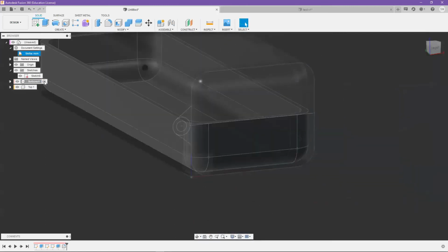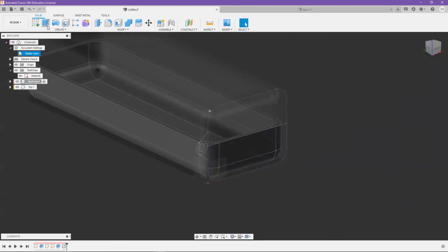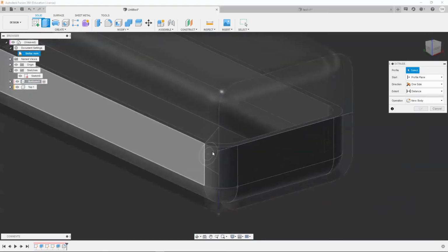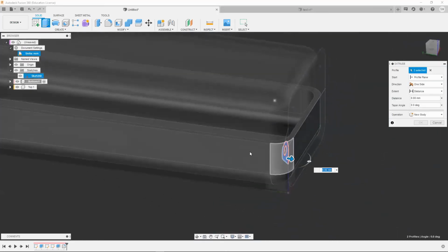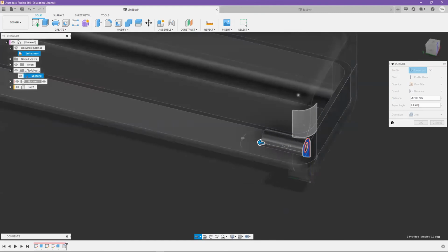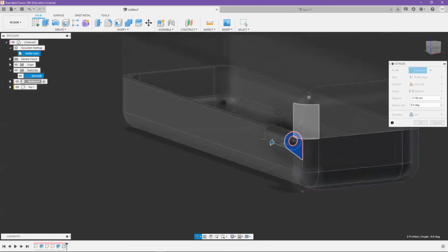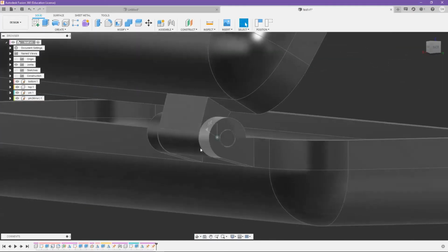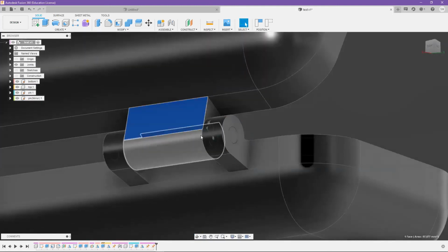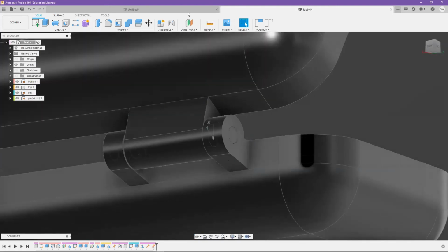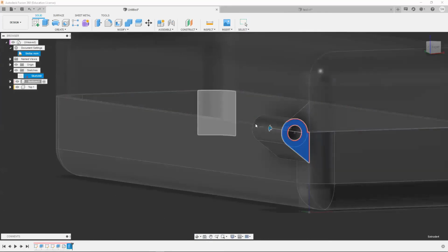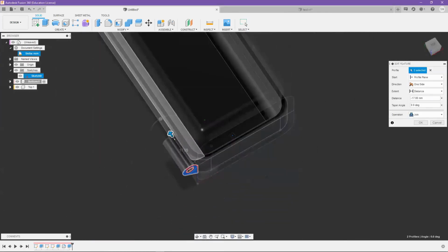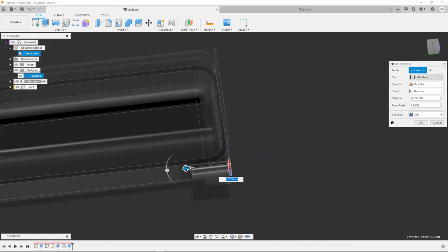So now we're already in the bottom workspace. That's fine. If you press Q or go into extrude, select this and this for the hinge mechanism on the bottom. If you drag this, you can kind of see what I'm going for. I'm going for this bottom part right here, or this top part. It could be either or, but it's just going to connect to the bottom portion. But the positioning is all wrong.